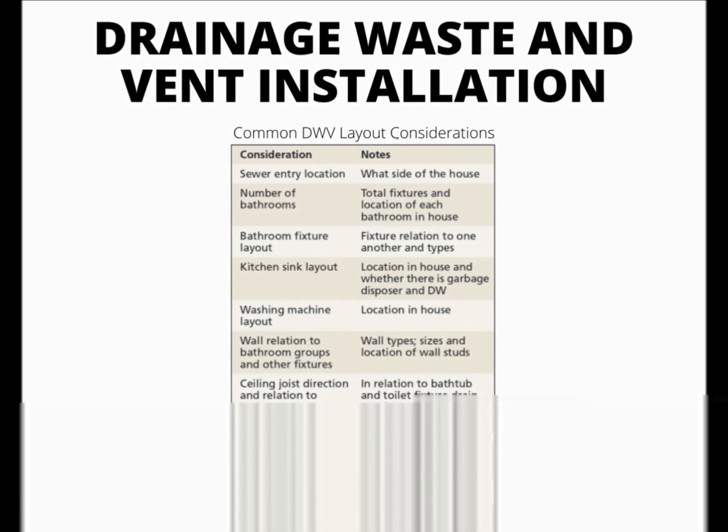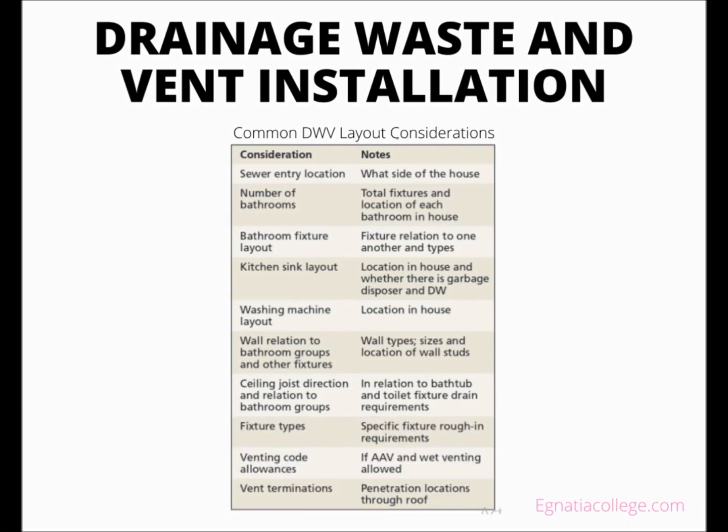A plumber must consider all aspects of a plumbing system route before beginning the layout. Every job site has unique layout challenges. A plumber begins by identifying and laying out the fixture locations. Knowing where the sewer enters the house establishes the flow direction of the building drain.